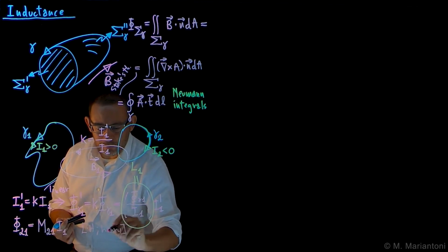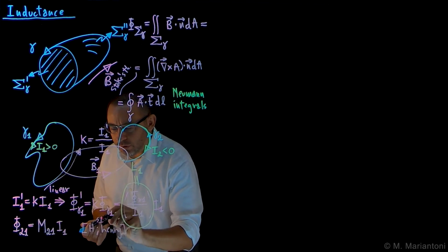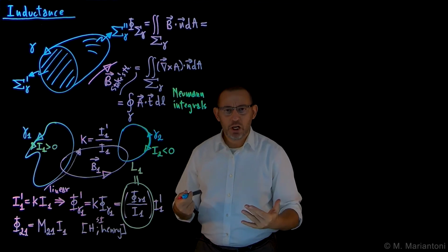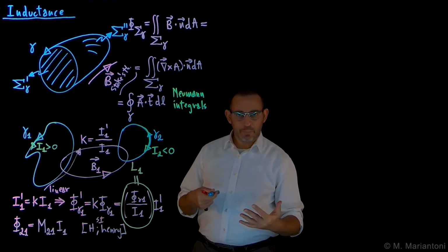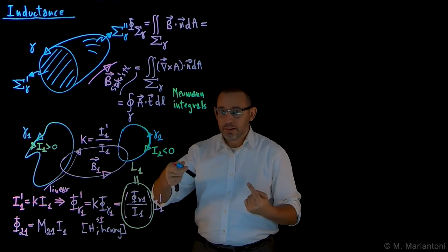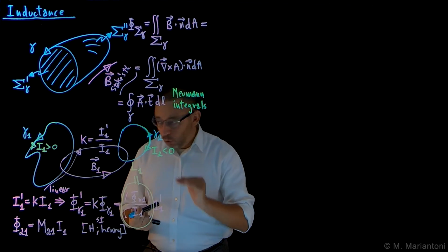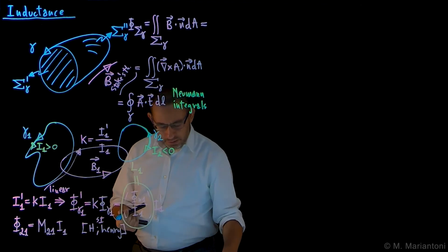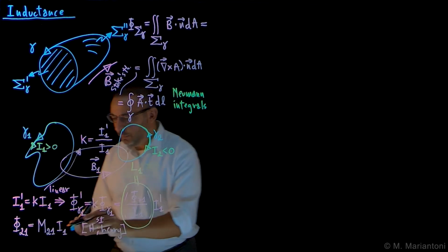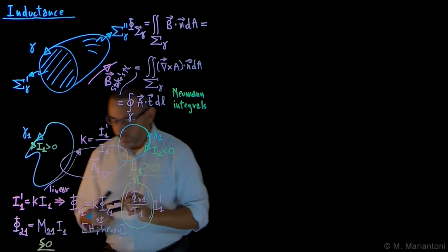And when you write it in full, you don't capitalize the first letter in SI units. So it's just henry like that. All right. So we will come back to this concept, and eventually we're going to write down a system which relates the flux on the first and second circuit by means of their self-inductances and mutual inductances. As it turns out, the self-inductance is always a positive quantity. So L must be positive, always. Whereas the mutual inductance can be negative. Can be both.